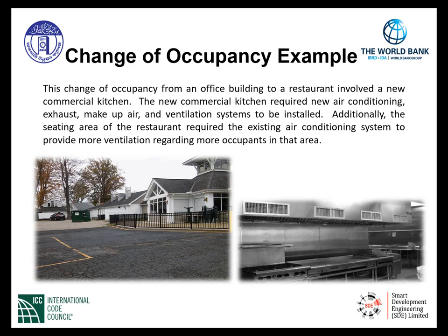This is a mechanical ventilation system that brings in outside air. It was analyzed and modified to introduce more outside air in liters per second and was calculated for the occupant density given this new change of occupancy.